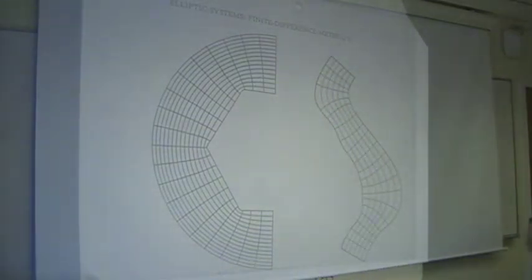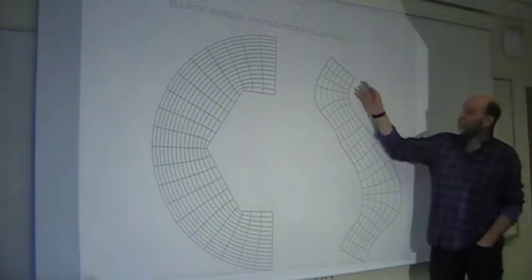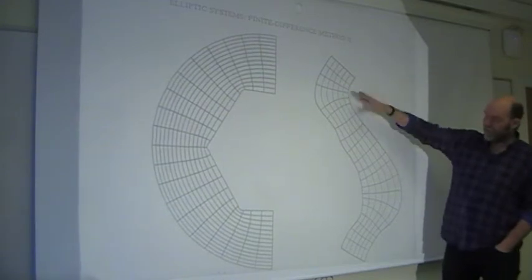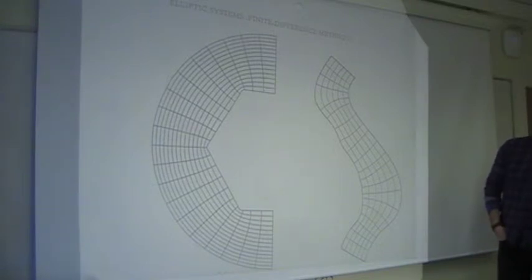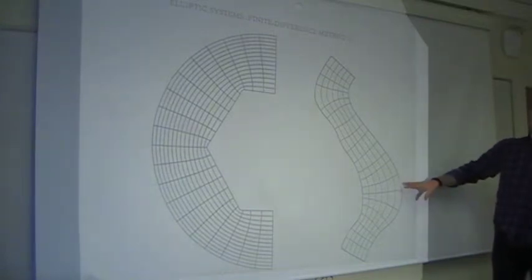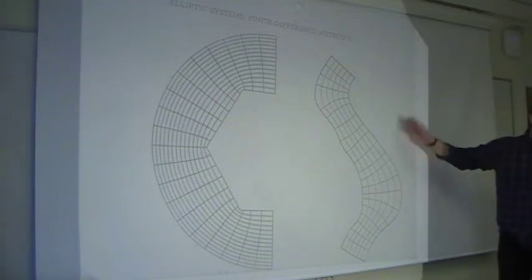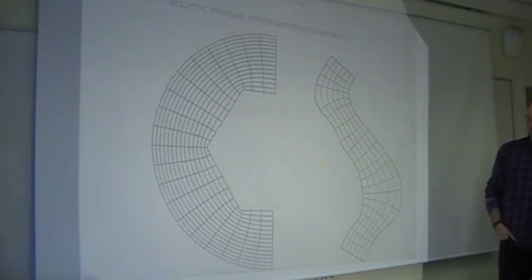More unstructured mesh systems. Now, these examples are still structured meshes. They have the same number of cells in two directions, only the directions have been twisted a little bit, but it's still structured. To create such mesh systems, typically what you do is you solve the Laplace equation. Think of it as potential theory flow, not viscosity.